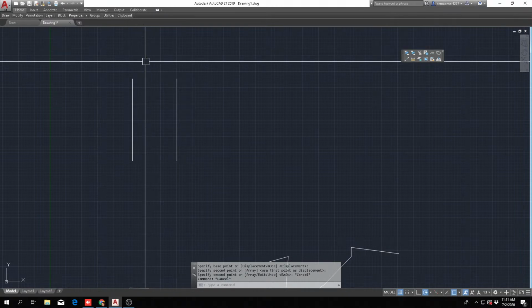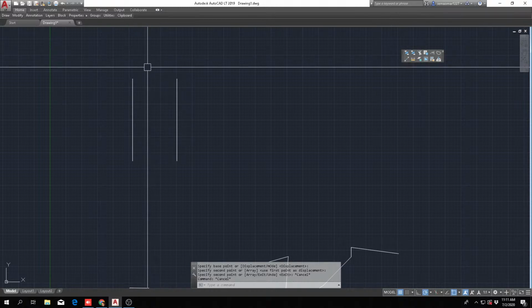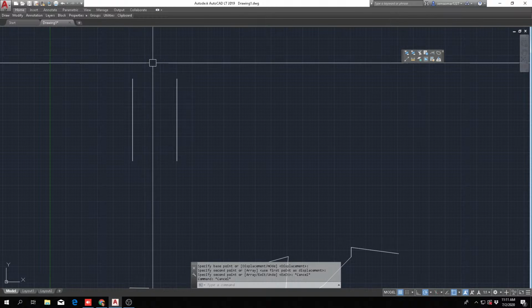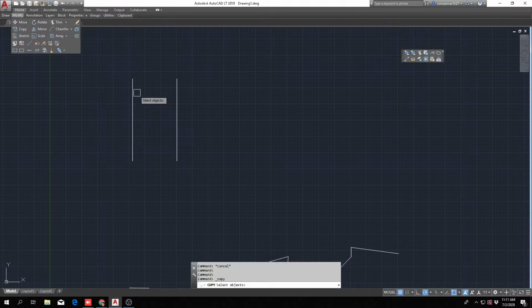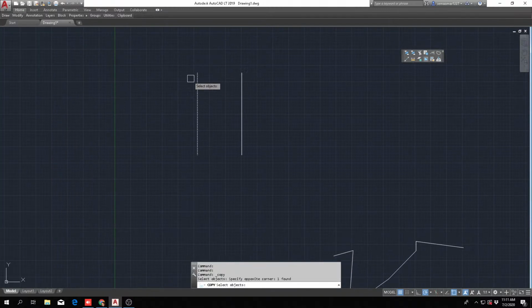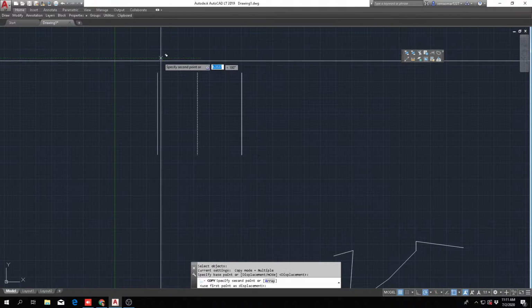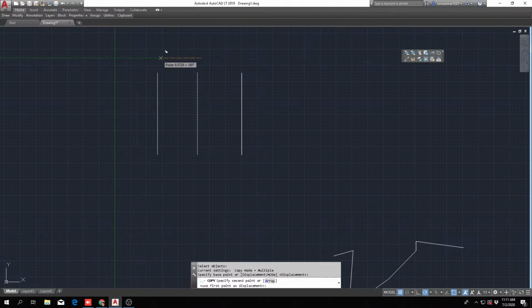Every time in all the tutorials, I'm gonna tell you this, because if this is the first time you jump in, you might want to look at the other tutorials to set up your AutoCAD. It is useful to have your polar tracking set up already, because you see how it just snaps to horizontal, and you can copy your lines straight.